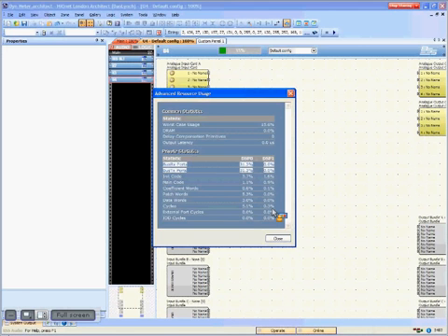Now that also brings up an important issue on the BlueLink. Blue 160, just like in the original series, the Blue 16, because it's not using DSP power to talk to the CobraNet module, has more DSP power than a Blue 80, really. Because you give up 10% of your power in the Blue 80 just to talk to the CM1. Blue 160 can process more channels of BlueLink audio than a Blue 80.